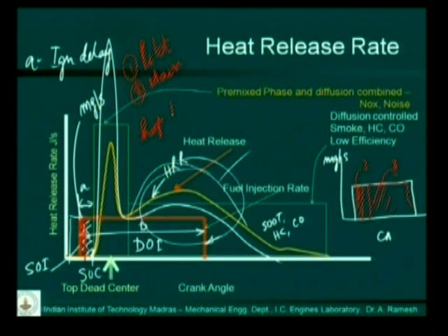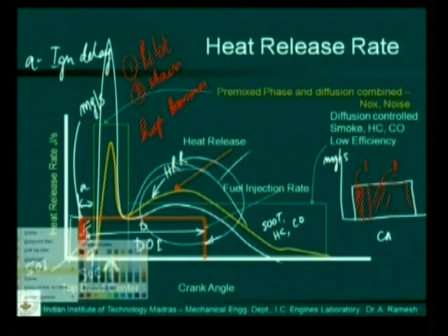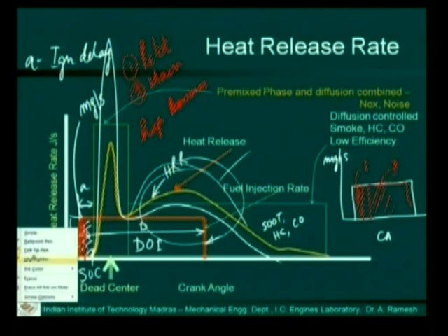So the second injection and the first injection both occur at high pressures. And what is the benefit of using high pressures? These high pressures can give you very good atomization, and very good atomization can ultimately end up in a very good diffusion combustion phase.